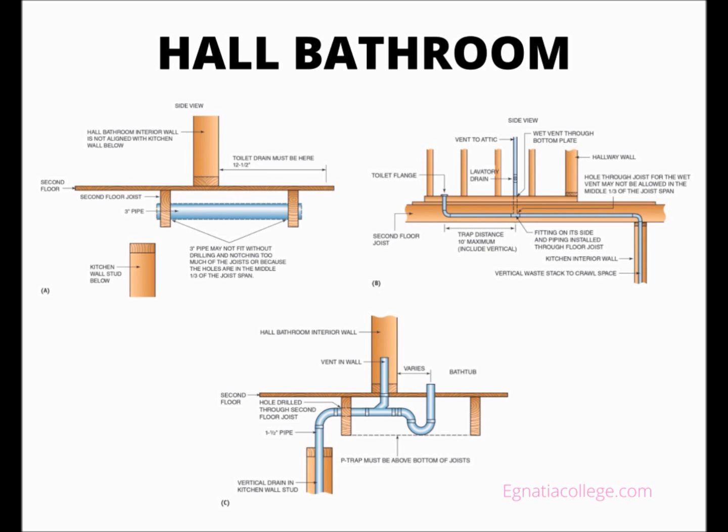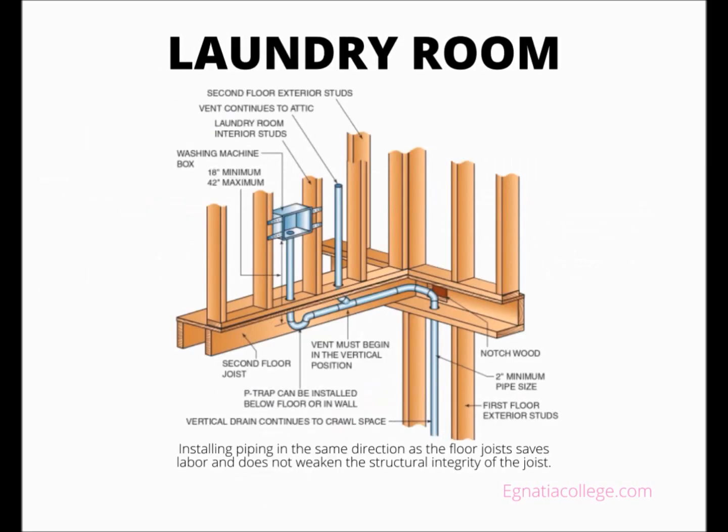Most codes dictate that 2 inch pipe must slope 1/4 inch per foot. Connecting it to the same piping as the toilet would place the drilled holes for the lavatory through the floor joist in violation of the top 2 inches of the floor joist. Not all bathrooms can be constructed as designed. A plumber might have to provide an architect or general contractor with possible design changes.